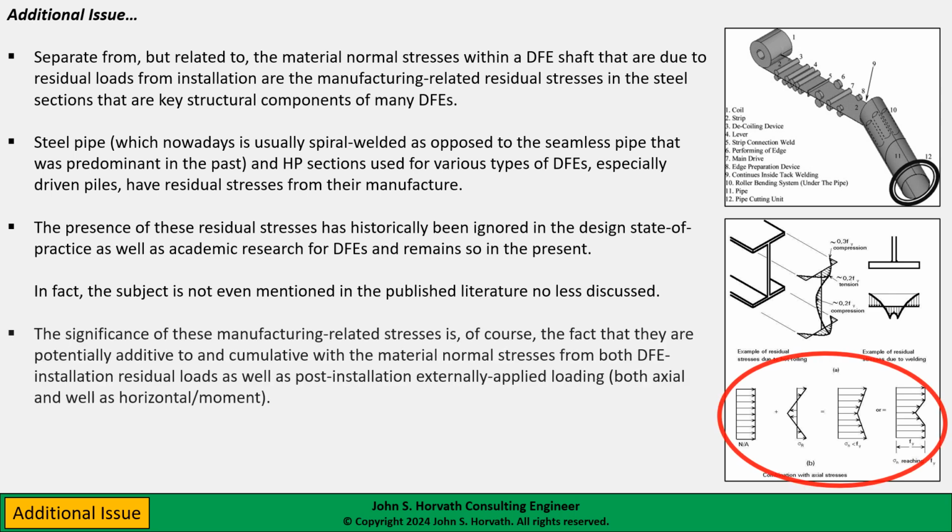So I'm mentioning it here because obviously these manufacturing-related stresses, whether from rolling or cold forming or welding, they are, in principle at least, or theory at least, additive to the material normal stresses from residual loads from installation, as well as the externally applied loads, both axial and horizontal moment.